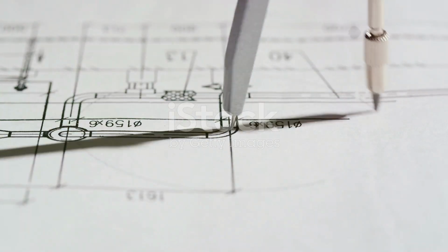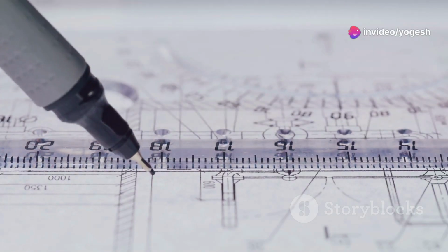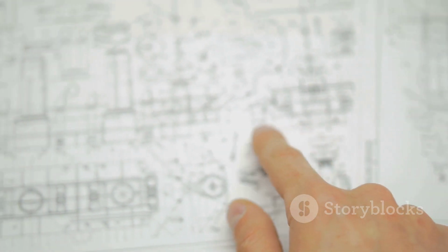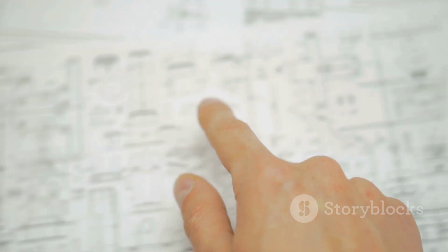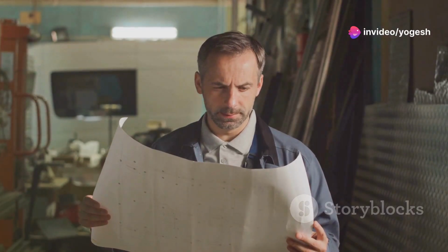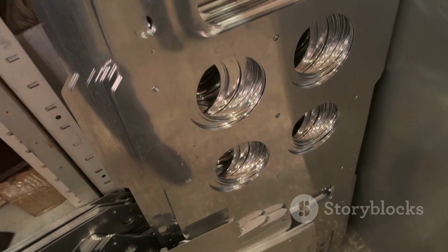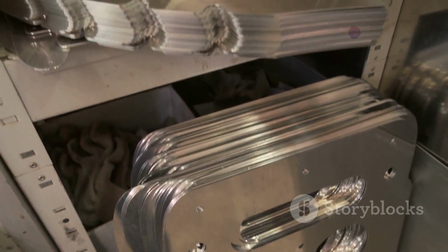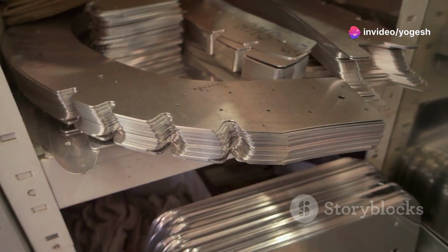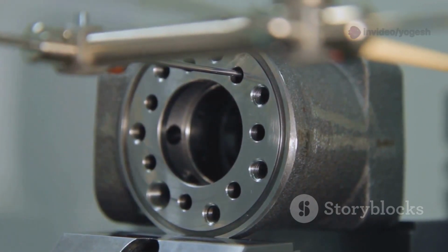First up, let's talk about one of the most common and costly mistakes in engineering drawings: missing or incorrect dimensions. If a dimension isn't shown on the drawing, for all practical purposes, it simply doesn't exist. The shop floor can't read your mind. Machinists can't guess your intent or fill in the blanks. They rely on your drawings to be complete and unambiguous. Missing just a single number can turn a $500 part into useless scrap, wasting time, material, and money. It's a mistake that's all too easy to make, but expensive to fix.